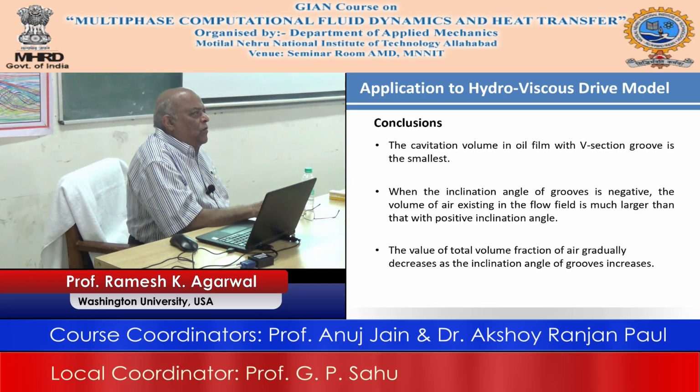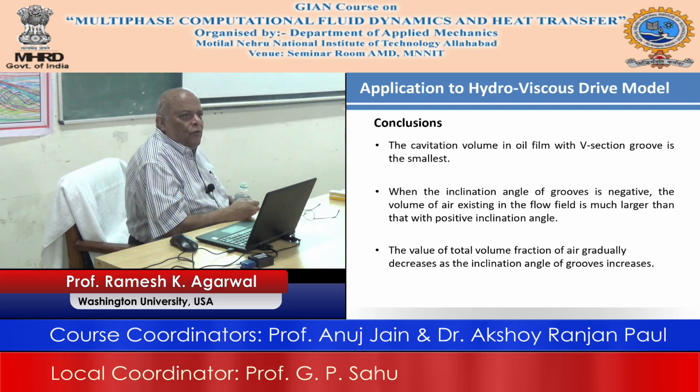And that is how people model cavitation today in all industries. All right. If you went with the bubble route, then you would not be able to do this problem, and that's not necessary. So what you are using here is a two-fluid model with a VOF. That's all.